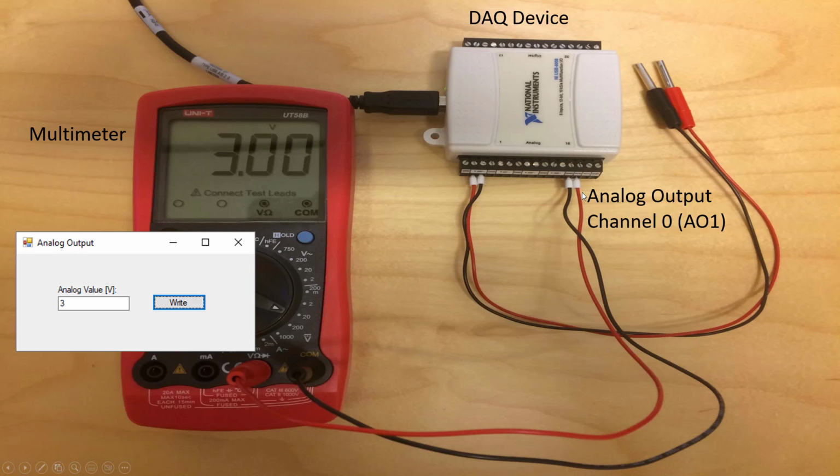So here I have connected and use the analog output channel number 0. This DAQ device has two analog output channels. So this is analog output channel number 0, and these two are analog output channel number 1. Here I have used analog output 0. So basically here is a spelling mistake. So these two connectors are analog output 0, and these two connectors are analog output channel number 1.